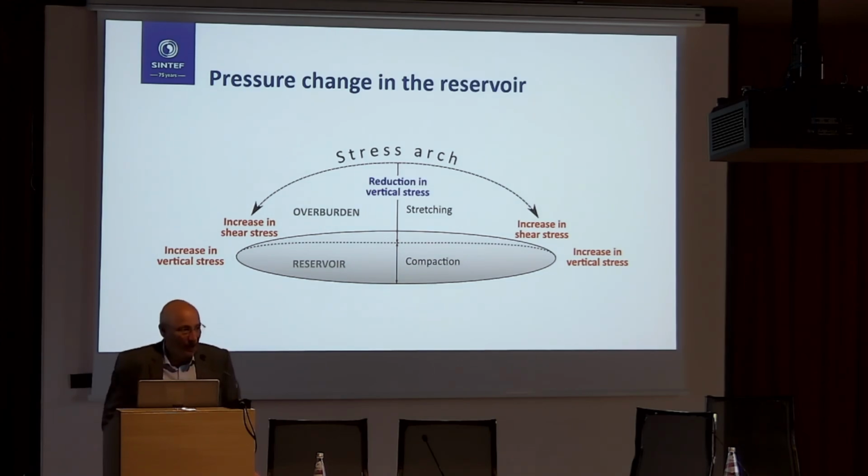But basically, if we assume a rugby ball type of reservoir, which we know all reservoirs are absolutely like, looking at first depletion, so compaction, intuitively, if we're looking at a point just above the reservoir in the caprock, we will have some vertical stretching. So we expect the stresses to react to a stretching of the material.